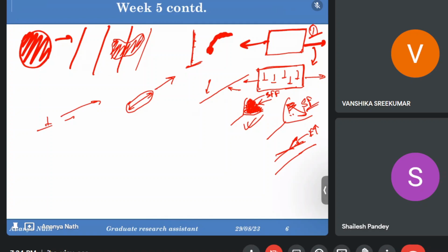But here a lot of dislocations have been piled up at one place. There are two types of dislocations, and they have opposite signs also. So due to a lot of dislocations and the higher dislocation density, it will have a different condition for them. It needs a different condition to move.